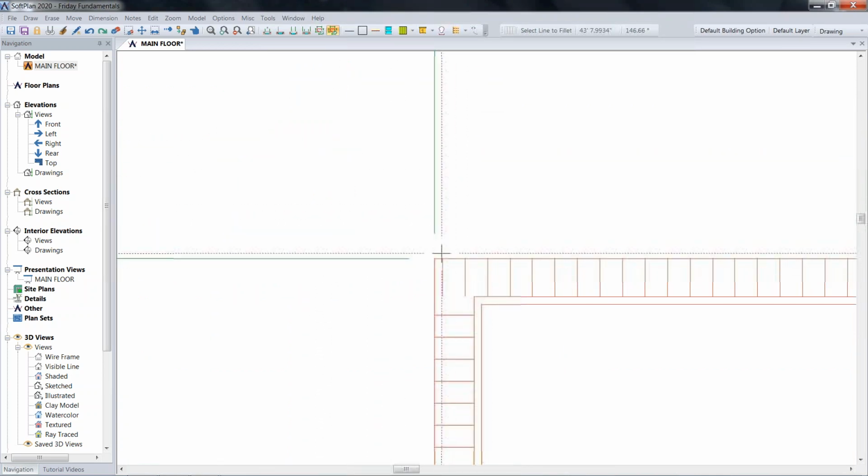One last word on dimensions. We are dimensioning to the outermost face of the outermost load-bearing material, outside face of the block. Not brick, not stucco, not siding. Structural. That's what we're doing.